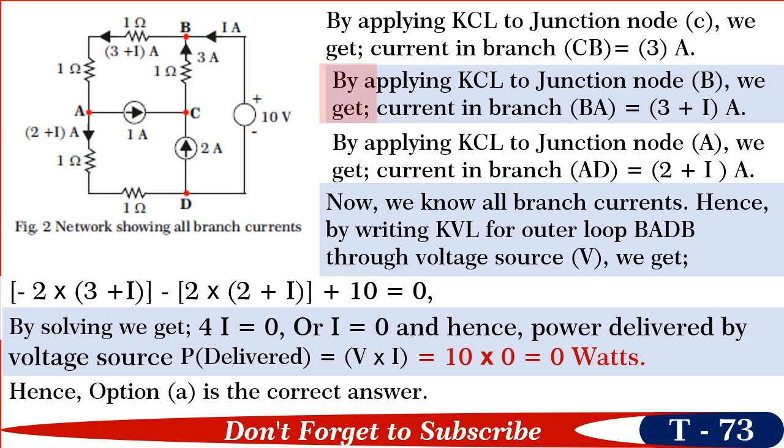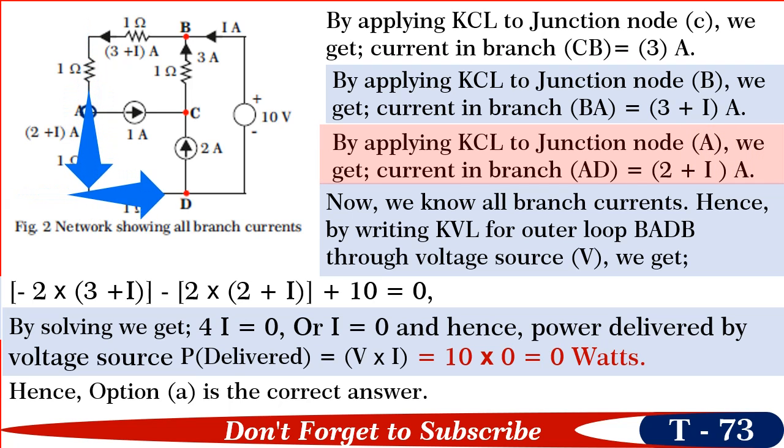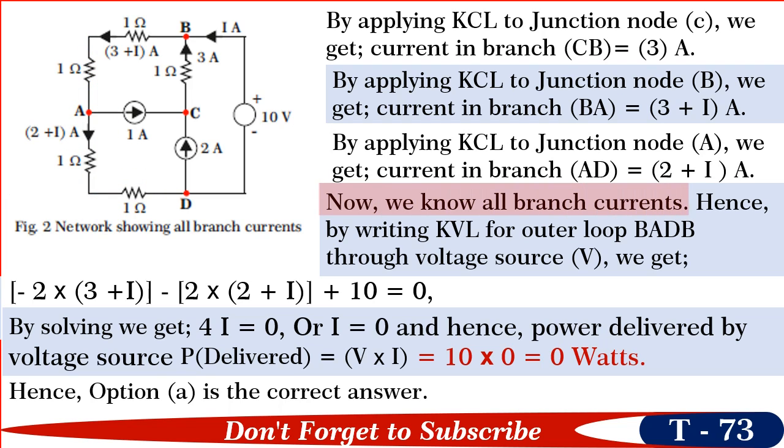Next, by applying KCL to node B, we get current in branch BA is equal to 3 plus I amperes. Similarly, by applying KCL to node A, we get current in branch AD is equal to 2 plus I amperes. Now, we know all the branch currents.